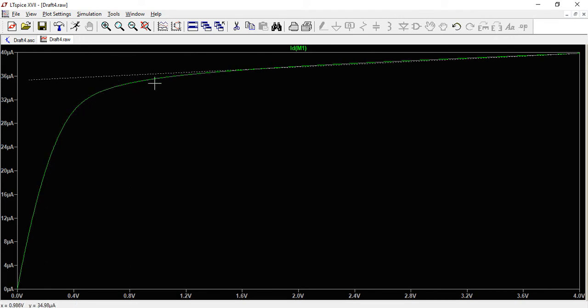You can see a lot of this is happening in this region here, which is roughly in the vicinity of 0.8 of a volt. It's not a precise way of measuring VDSAT. The theory tells us VDSAT occurs at exactly VGS minus V threshold, but as you can see, it's impossible to pinpoint exactly when you can say you're right at the edge or the transition between saturation and non-saturation. So the best we can achieve with a simple analysis like this is just that straight line there, and we can see that it's happening in this region here, roughly in line with what we expect.